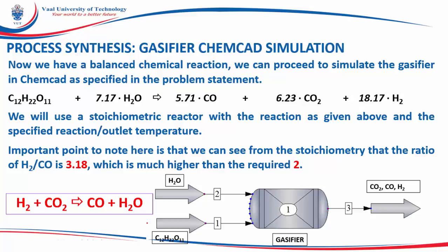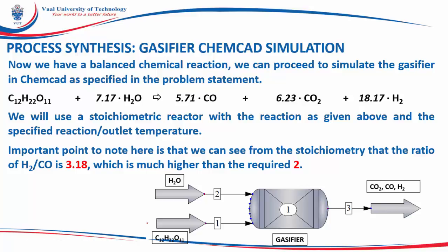This is your design. You can think what needs to be done. Is it worth getting an extra reactor, which is the water gas shift reactor, with all its accessories, such as addition of water, maybe temperature increase, maybe pressure increase, and then the separator downstream to shift the excess amount of H2 towards making CO, so that you produce more methanol in the end? Or you will use H2 as it is.